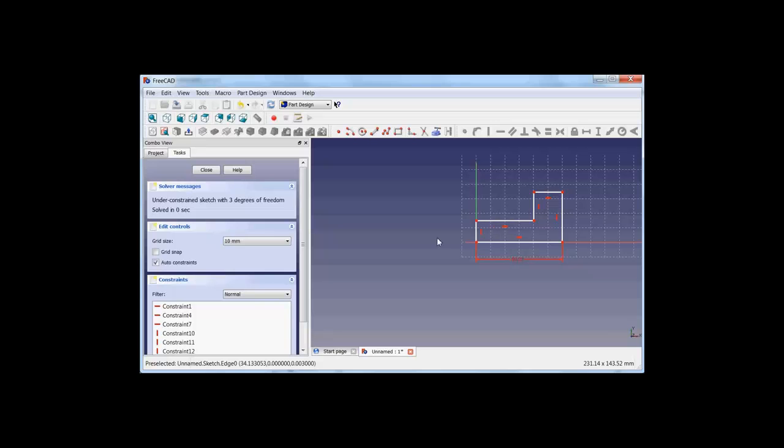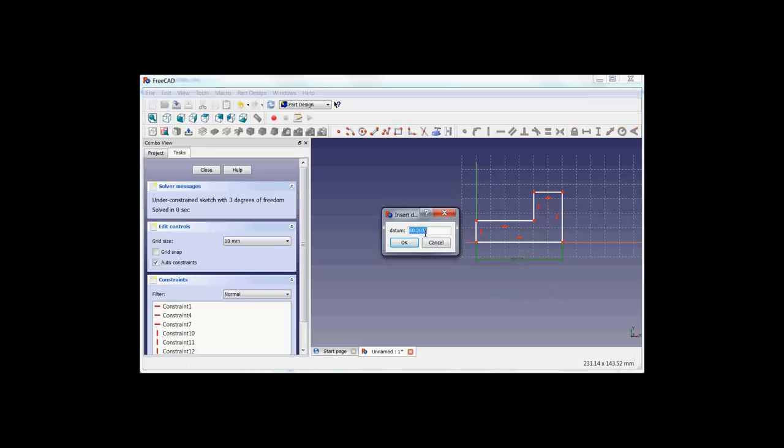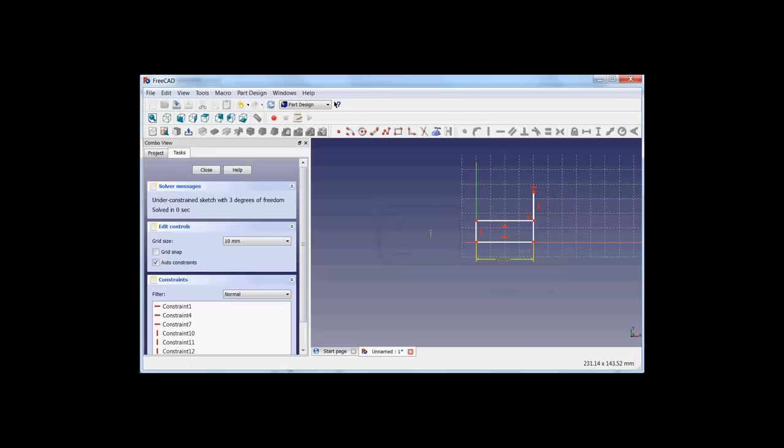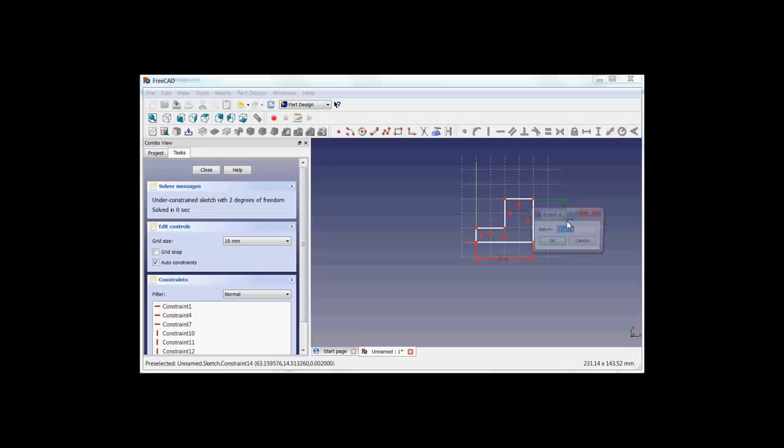And then the dimension comes, it's being placed rather randomly, so you can pick it and drag it outside of your sketch so it looks a bit nicer. And if you double click it, then you can change the size of it. So let's make that 40. To keep it nice and tidy, put it a bit there. And you can basically, like clay, put it in a way that you like it. And the exact dimensions then follow later. For example, if I now put the dimension, then it says 29.8. And of course I say, no, I just want to have it 30.